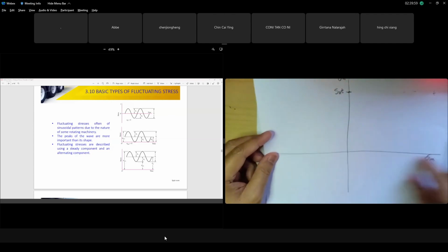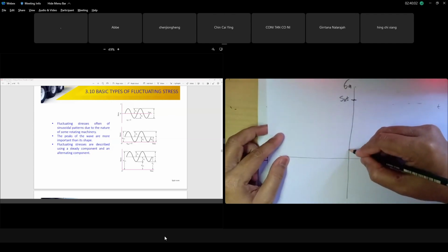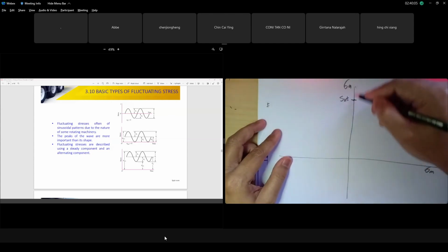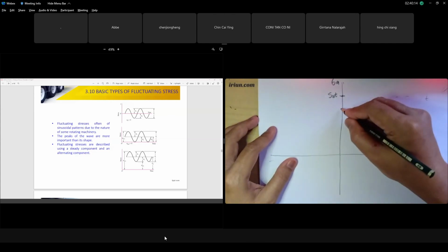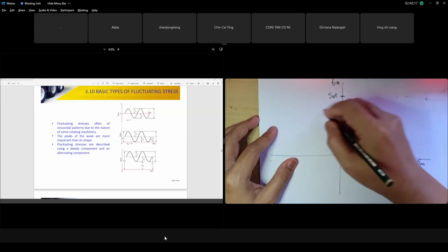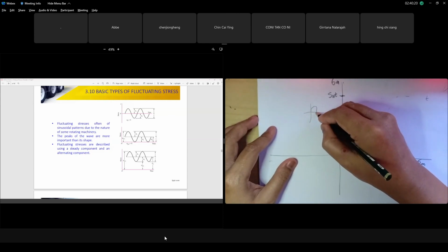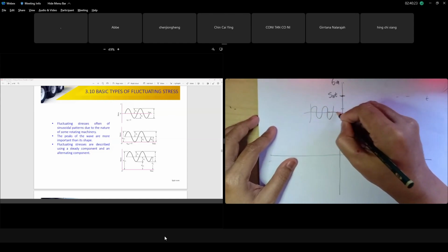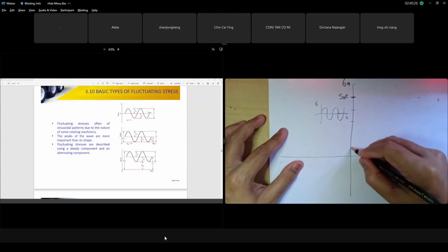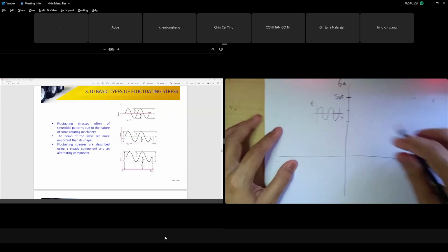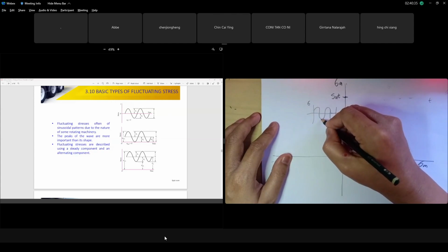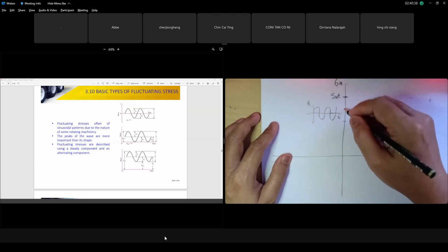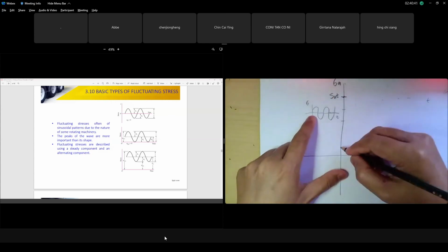When you plot sigma mean against sigma amplitude, also called the sigma alternate graph, all along this line sigma mean is zero, right class? All the stresses you calculate that are completely reversed over time lie along this line where your mean is zero. Maximum and minimum have the same value but opposite sign, so your mean is zero.